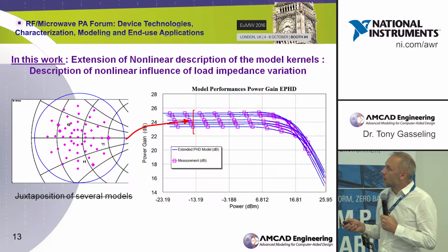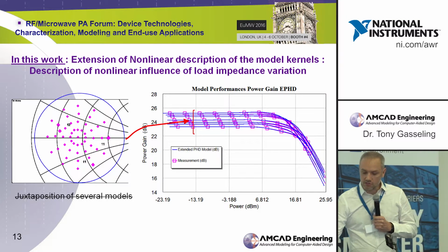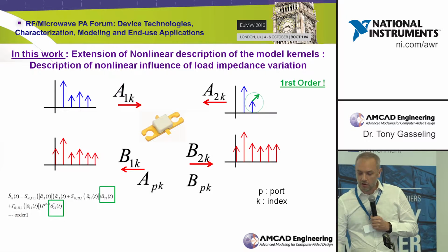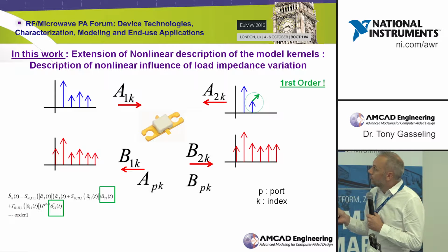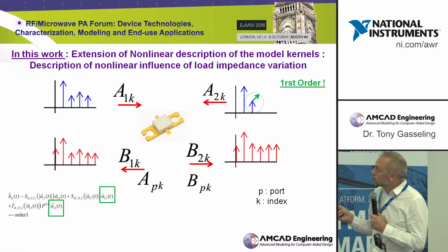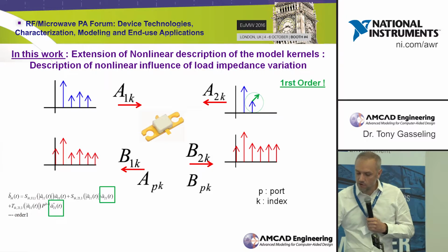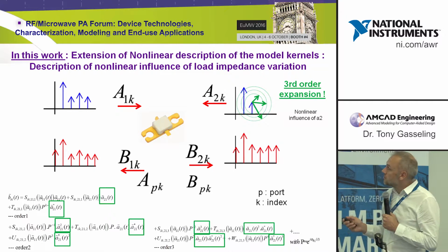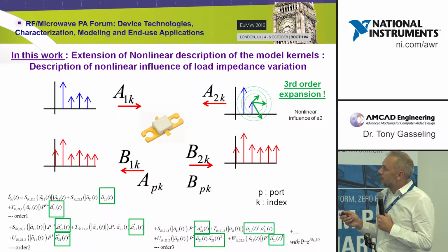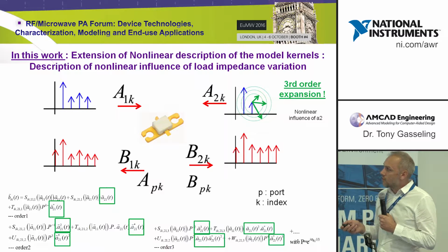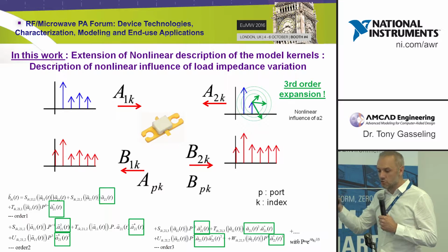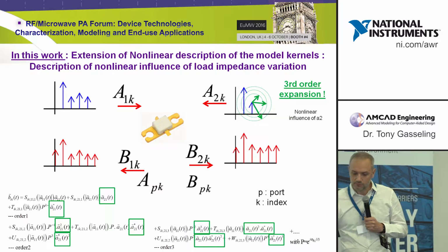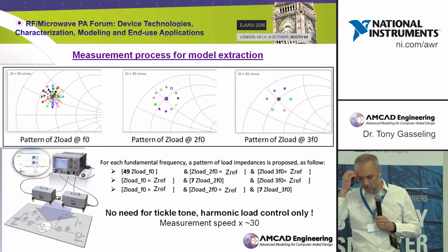So we have extended the description, the formalism. So rather than just using the first order probe tone in order to probe this nonlinear behavior, we are using a third order expansion, in fact, to add terms in the model in order to better define the nonlinear behavior around a nonlinear state, especially regarding the loading conditions.